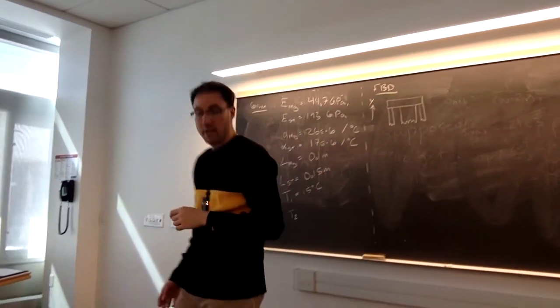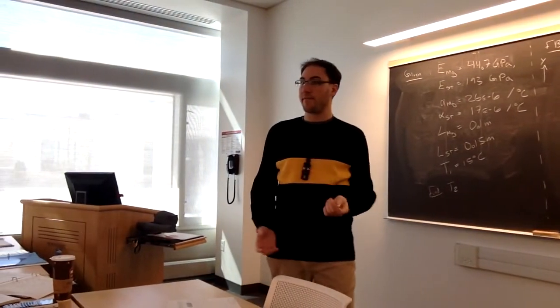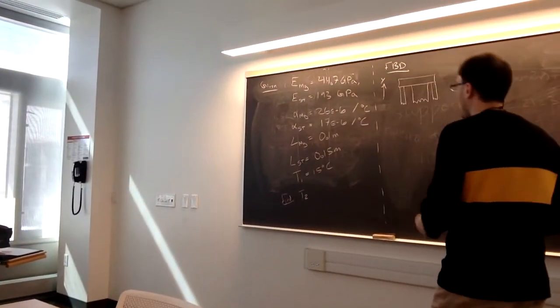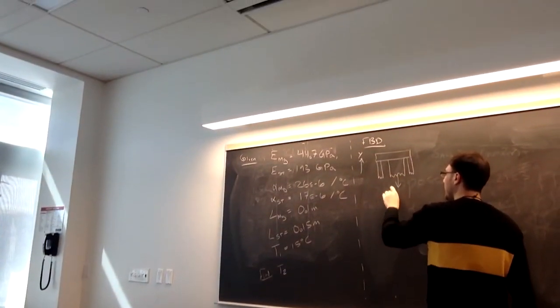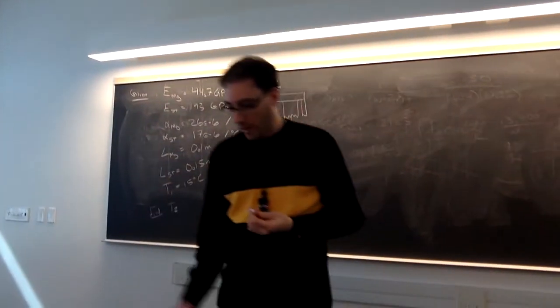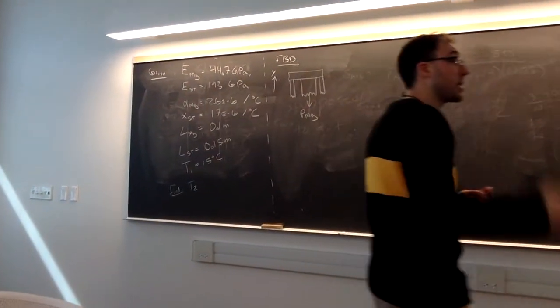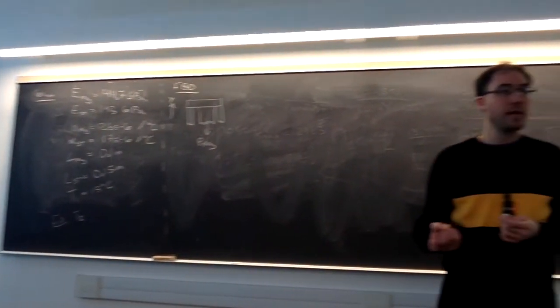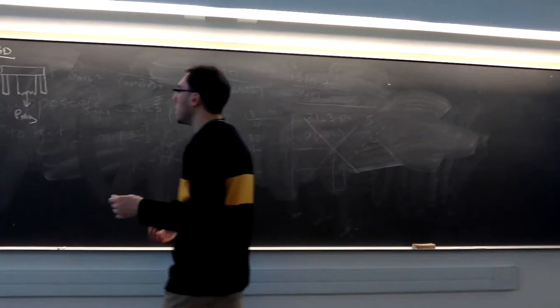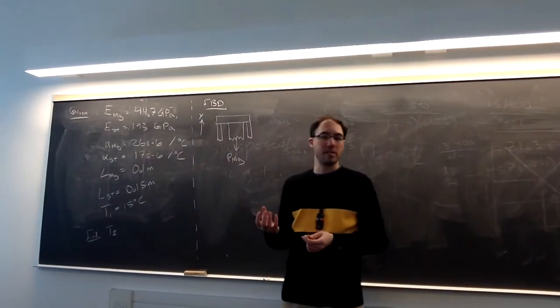Right, so we make our cut. There's no external applied forces. All of the stress is coming from the thermal effect. We're cutting through the magnesium, so we can see the internal load in the magnesium. This is where we now have a choice. We can either treat the steel bolts individually, however, through symmetry, assume that they're behaving the same, or treat the steel as one collective material.